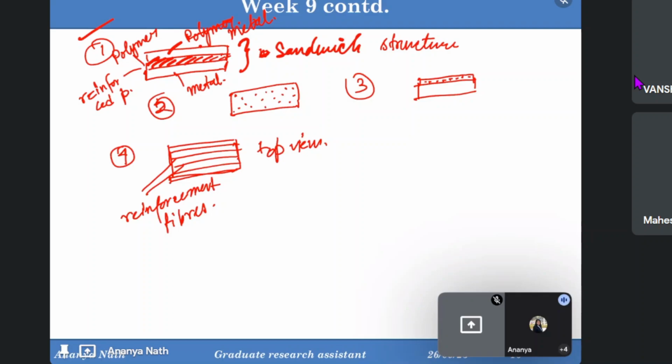The well-known composites are made up of polymer only. These days, researchers are trying to develop the metal matrix composite, because mixing some reinforcement particle in the melted metal is way tougher than with polymers, because of the high melting point of the metals, which can melt the reinforcement particles as well. So you have to be very choosy in terms of the particle and the metal combination in case of metal matrix composite. So the next process was the solid state method.